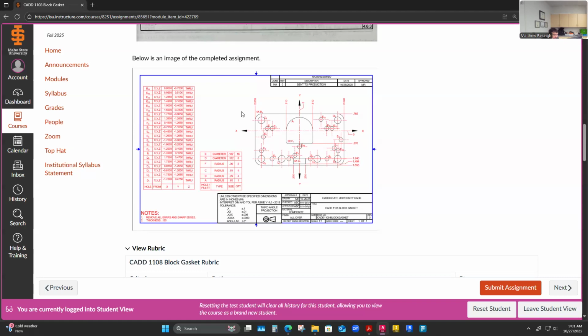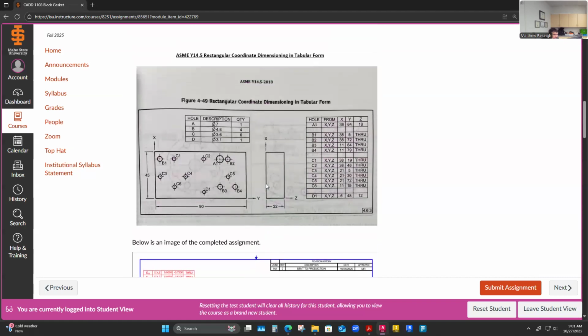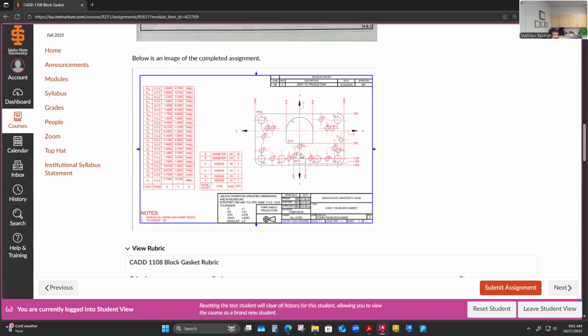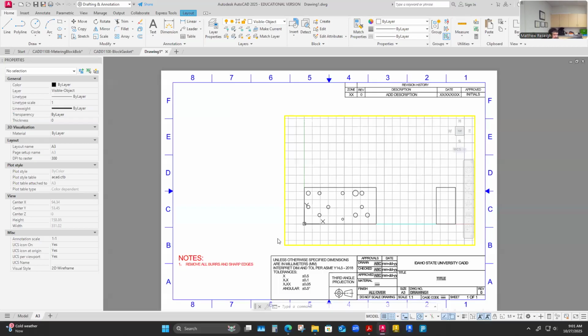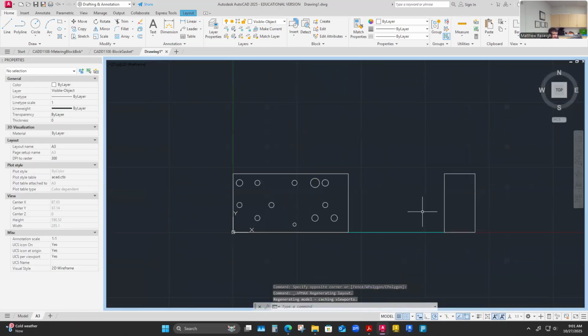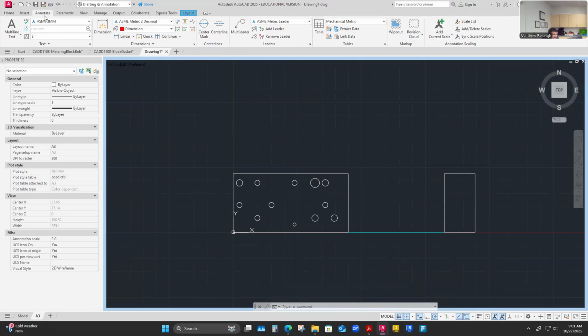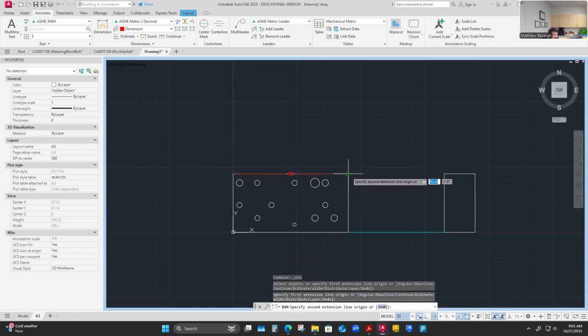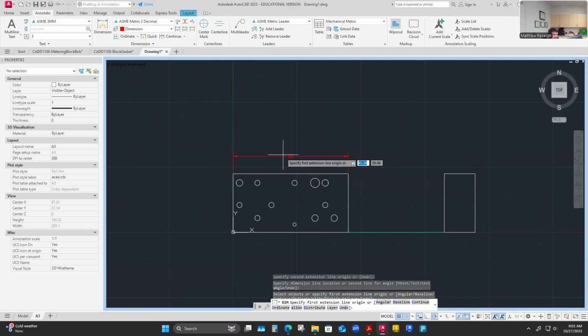This is just a little bit more complicated, and that's why I like to start with the one we are. But if those of you are working ahead, just watch yourself. Let me show you one more thing of where that's found. If I go back to CAD, and I was actually going to go into this block and use linear dimensions, but if I was pretending for a minute that I needed the dimension style for the other, on the annotate tab you have underneath here an ordinate style of dimensioning. So if I call this out here and I go to dimension and I'm on the ordinate style, it's going to call this out as not what I thought. So hold on just a minute.